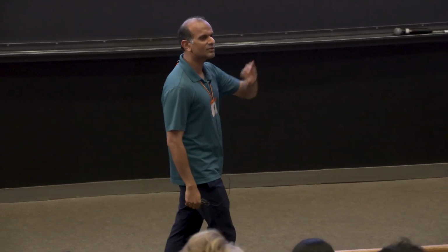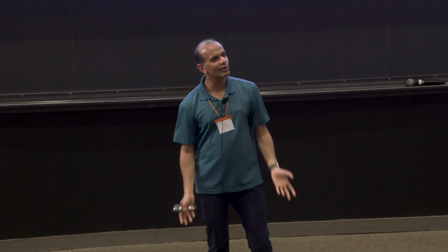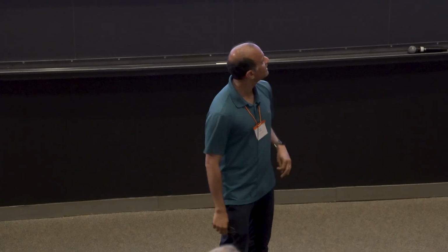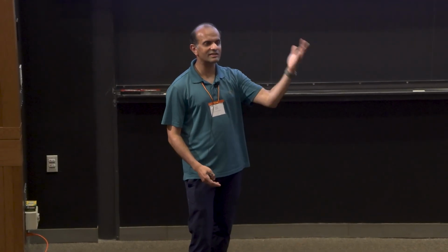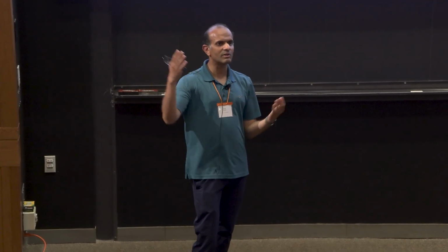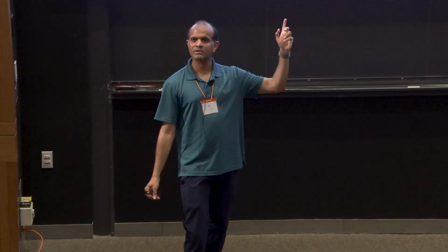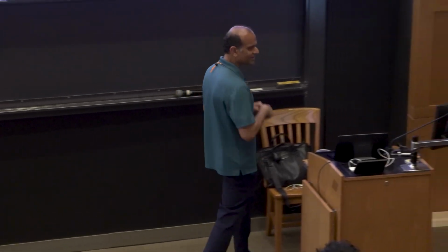So temperature of 2500 Kelvin and 300 Kelvin, the average is 1400 Kelvin, right? So the experiments will show 1400 Kelvin temperature average. If you do Reynolds average Navier-Stokes equations, you cannot get it. You'll either get the extinguished state or the burning state, but not the intermediate, which is not physically possible. So LES could capture this. This was a big revelation at that time. It was like an earth-shattering calculation. I just said that myself, but it's an earth-shattering calculation.